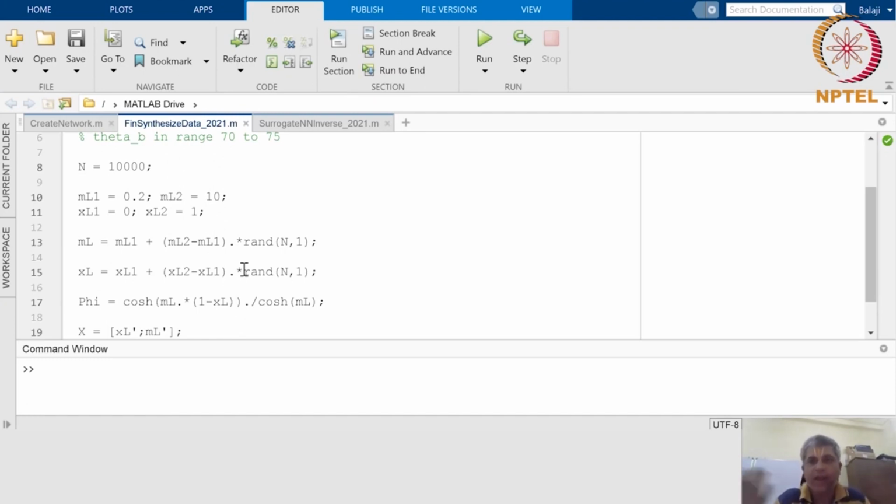Ideally, what we should be doing is we have some simulations. Many people do this. They have a simulation without the exact solution, but with a CFD simulation or something. They generate this data from past runs. That makes them a model. The advantage of the model is that it is much faster than the CFD simulation. A CFD simulation might take hours. A neural network will take seconds once you have trained it. Before that, you have to run it for hundreds of hours. But once it is trained, in any actual case, it can work much faster.